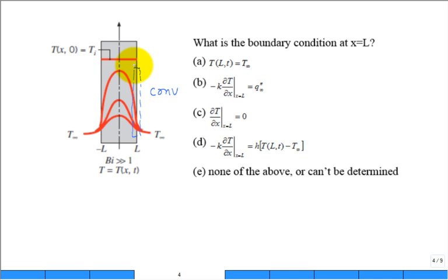On the right side, it's a little bit into the fluid. On the left side, it's a little bit in the solid. So how does it get out by convection? How does it get in by conduction? So at that boundary at x equal to L, we write that Q double prime conduction moving in the positive x direction is equal to Q double prime convection in the positive x direction, getting off of the surface into the fluid, right? This is the positive x direction.